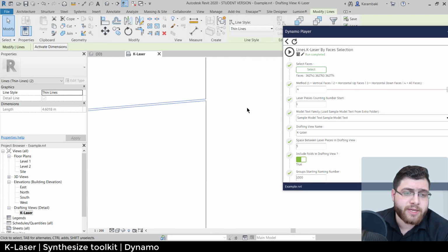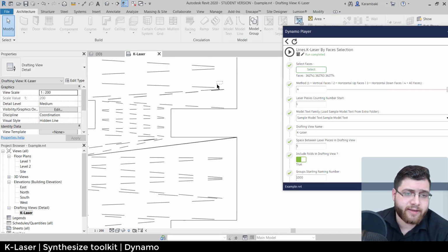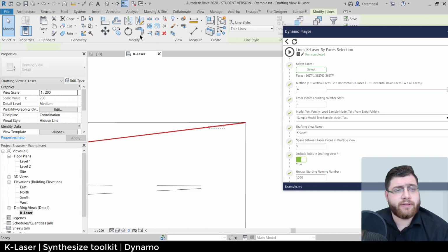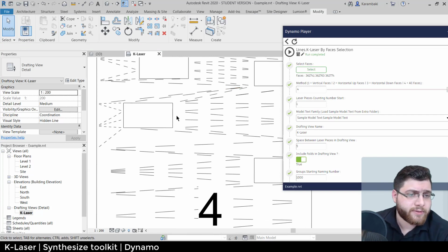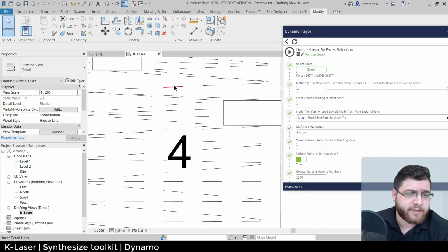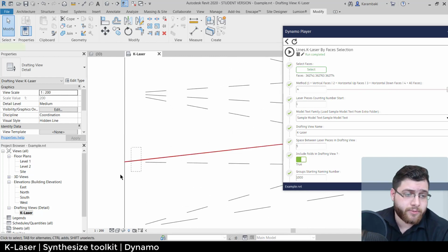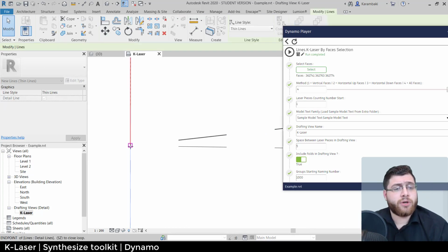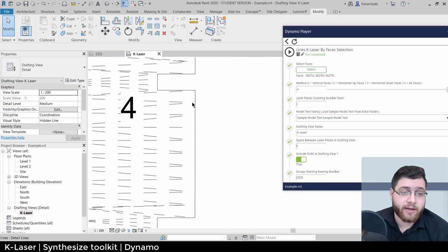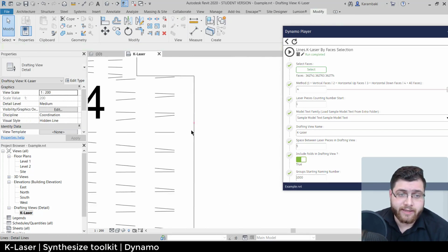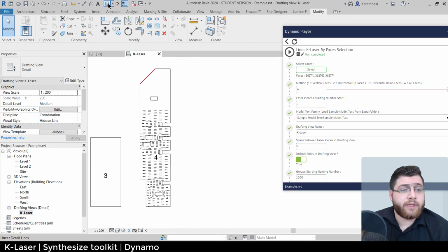So for example, if you delete this and join this with this, it might take a couple of, let's say, clicks, but it's pretty straightforward. And I believe that's it. Of course, when the time comes for the CAD export, oh, here's a problem too. When the time comes for the CAD export, you might need to do an overkill in AutoCAD because there are lots of lines over each other, so it needs an overkill. Alright, so let's head for the next example.